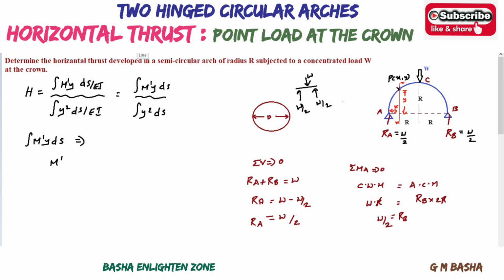One more thing I want to explain: this is a circular arch with radius r. If it were a parabolic arch, the y value would be based on the rise r and the full span length L, and the formula is y equals 4r by L square into x into L minus x. This is for parabolic arches. But for circular arches there is a small difference. Here this is of radius r; wherever you take, it will be in terms of radius r. For example, from here to here is also radius r only. So what about this distance from here to here?